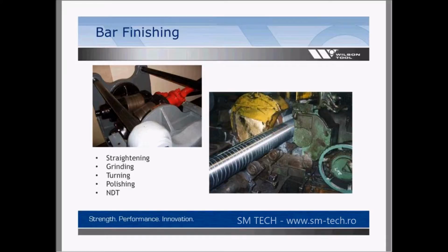The critical part about the bar itself is you want to have that nominal size and consistency all the way through the bar. When you're sticking it into a lathe and you go to finish up something different and make it a smaller or usable part, if you don't have that consistency, you're going to get some issues with size and possibly damage your tooling and your machine.